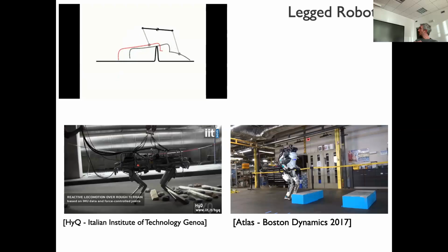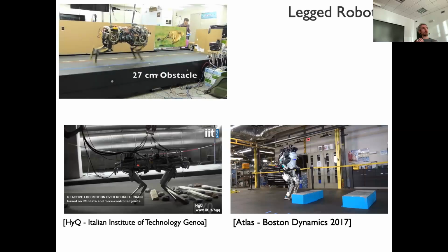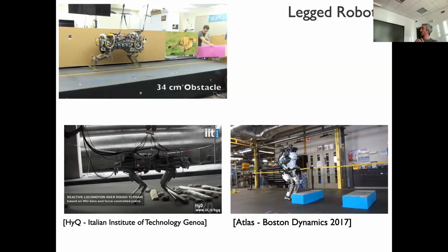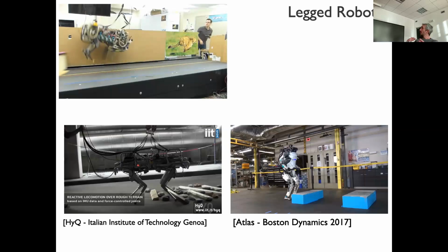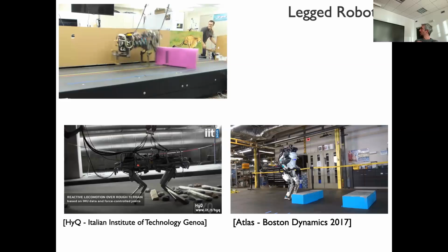Because basically these people had the idea of using much larger motors and much lower gear ratios, which makes the control of the actuators much simpler because you have much less friction. And that turned out to be a winning move to making this system behave nicely in the real world.